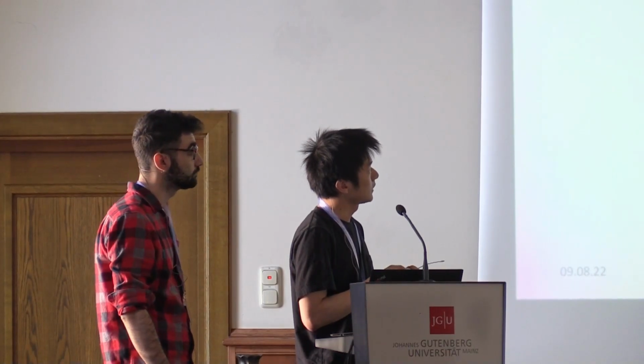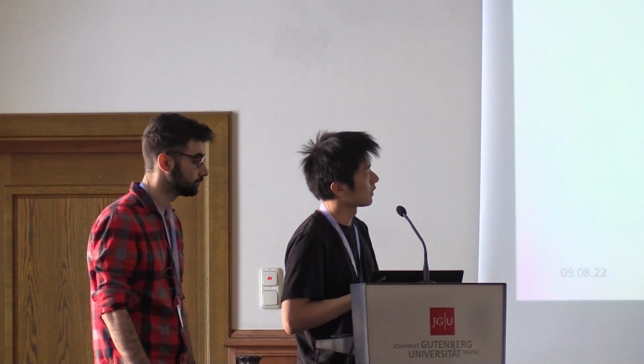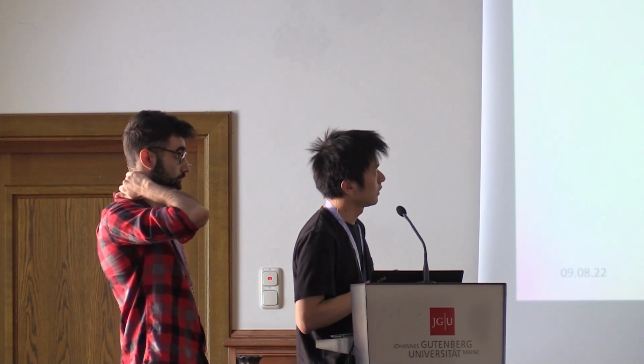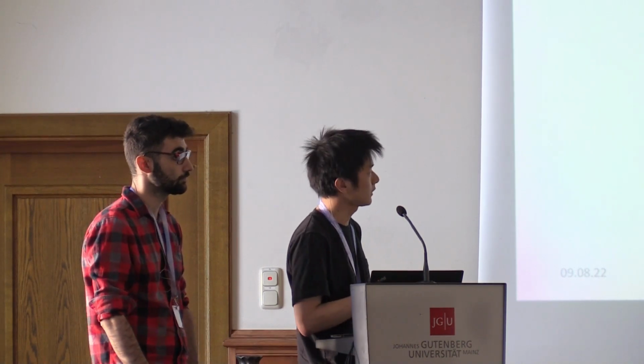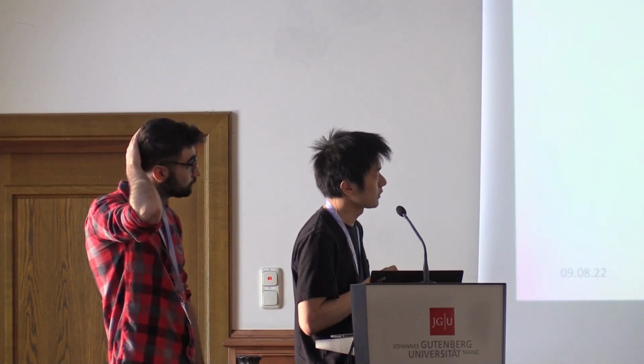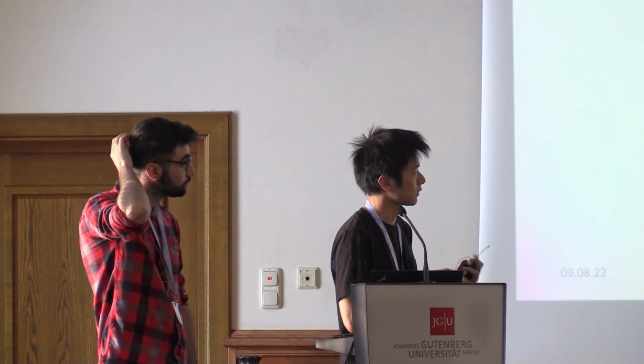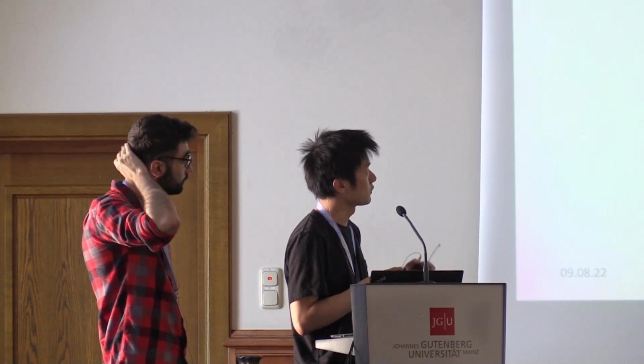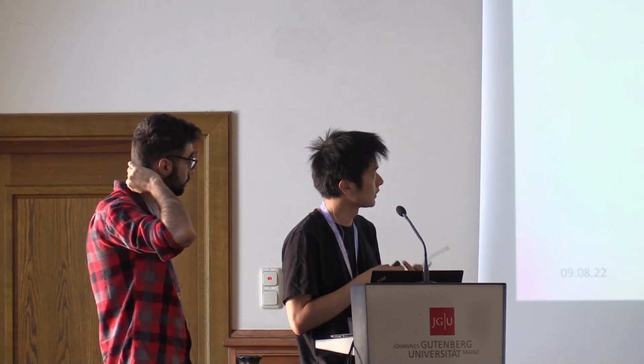Then both beams are interfered at this fiber coupler. We get the signal from this detector, and then it goes to a lock-in amplifier to do a kind of homodyne detection scheme. Then there will be a signal output after demodulation. This signal is also sent back to the fiber stretcher through a feedback loop called PID, which compensates for noise and keeps the interferometer at a working point.